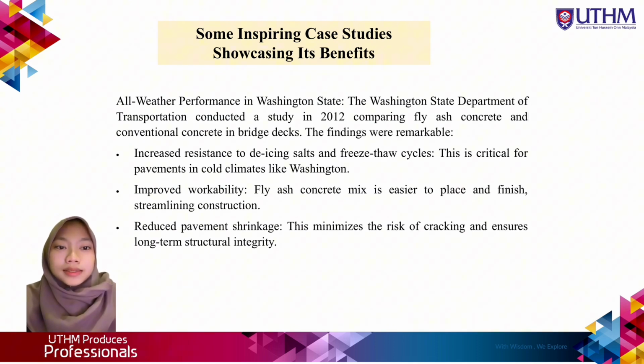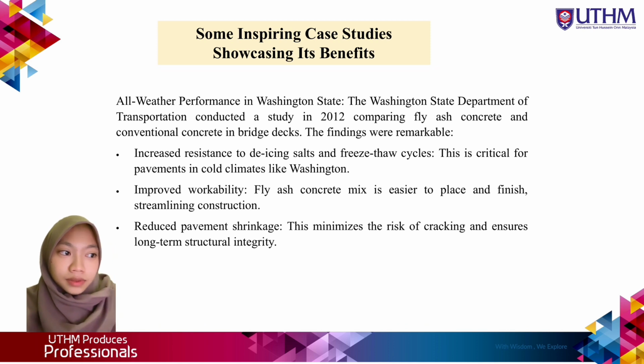So, the third is all-weather performance in Washington State. The Washington State Department of Transportation conducted a study in 2012, comparing fly ash concrete and conventional concrete in bridge decks, and the findings were remarkable: increased resistance to de-icing salts and freeze-thaw cycles, and this is critical for pavement in cold climates like Washington.